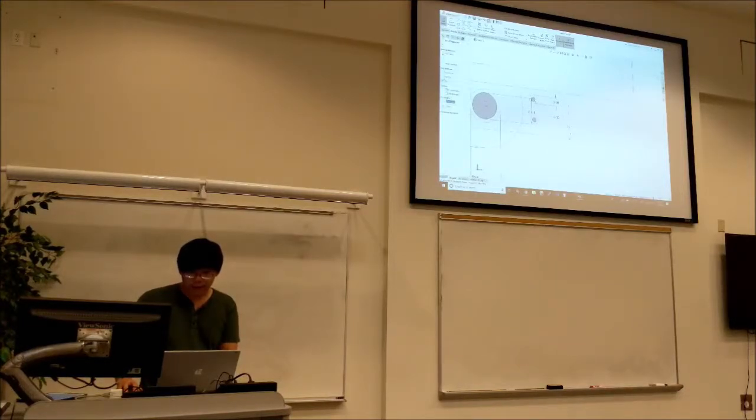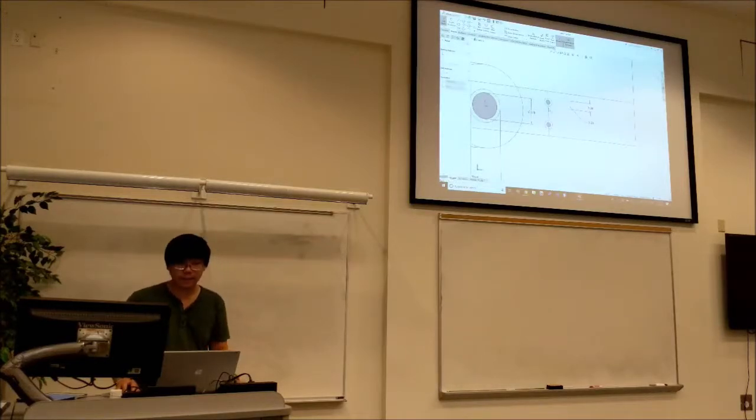And then if you set all these lines equal, because we dimensioned this line to be 2 inches, just divide 2 by 4. So that will set our hole pattern. So now this is 1/2 inch, and this is another 1/2 inch. So we can move these to be coincident with these points. And now it's set along the tube, right?